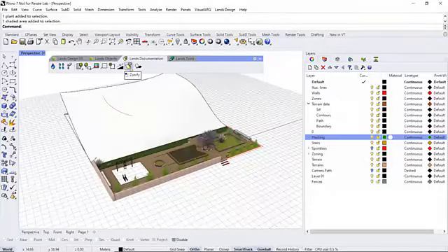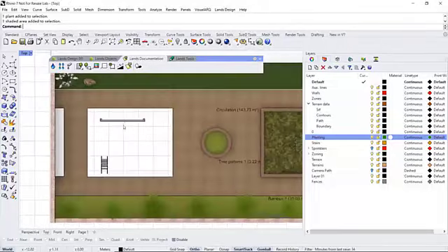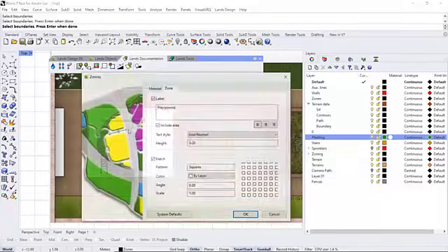We're going to use this zonify command, and basically we can insert the zone by picking an existing closed curve, or by picking an empty area, and it will find the boundary elements. So when we run this command, we can just pick an inner point, or in this case, I'm going to select this boundaries option in the command line, select this curve.